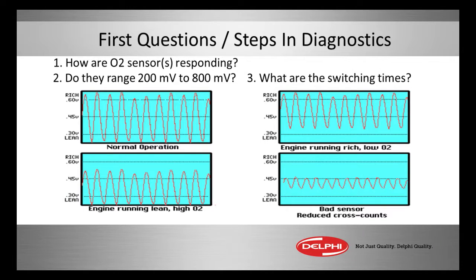And the picture on the lower right-hand corner, that's an O2 sensor that should set a code, but if it doesn't, don't pay attention to your fuel trim, because whenever you have an O2 sensor malfunctioning, don't pass go, collect $200. Fix that problem first. Misfire is the same way. Fuel trim can be worked on later if you still have a problem. So make sure you've got a good O2 sensor to work with.